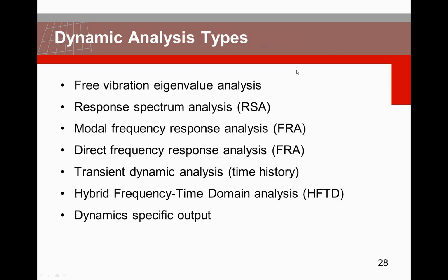Now we are coming to the dynamic analysis types that DIANA is offering. We have a free vibration eigenvalue analysis used to determine the eigenvalues and eigenmodes, a response spectrum analysis. Then we have a modal and a direct frequency response analysis, a transient dynamic analysis, sometimes called time history analysis.